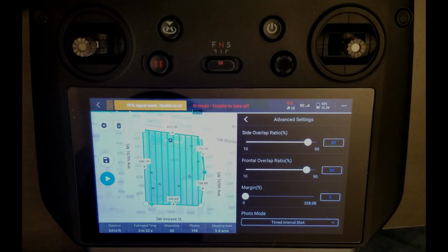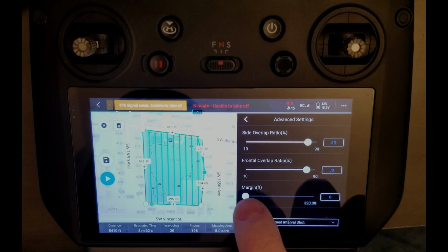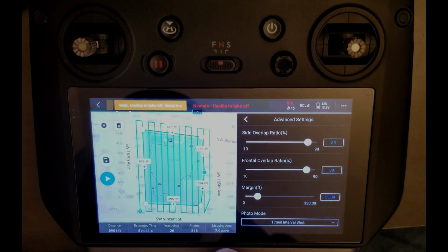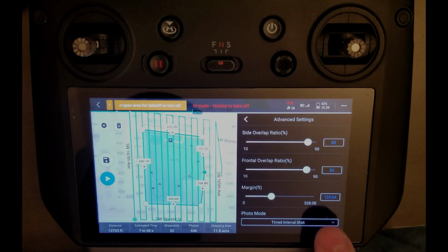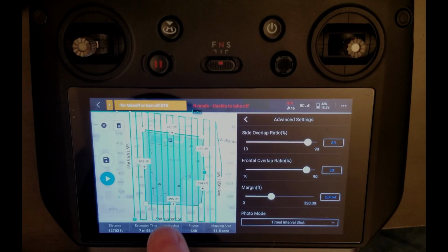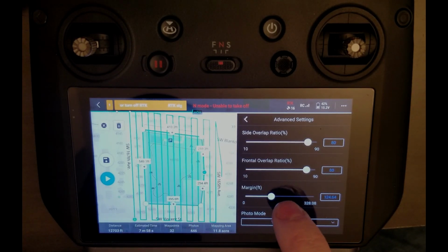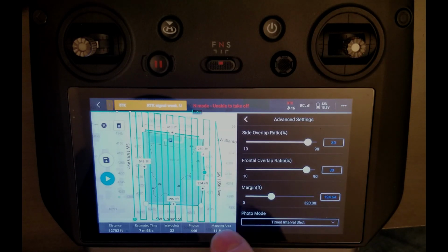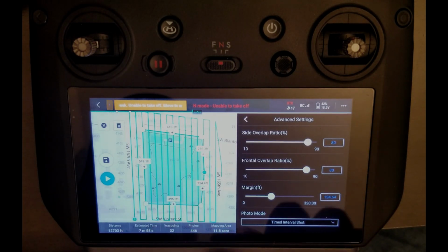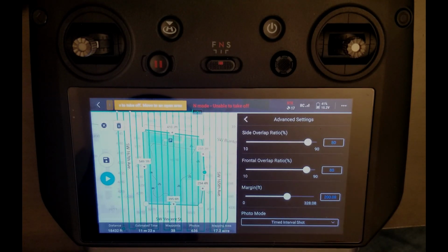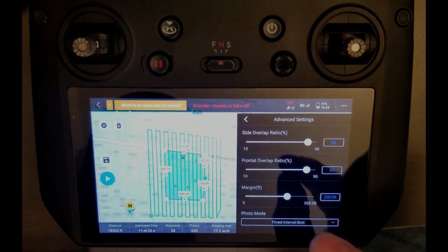With a slider bar or picking, I can now determine a distance beyond my project to add additional flight lines. As you see within this one, 124 feet beyond our project, I've now got additional flight lines. This creates an imaginary box 124 feet outside my project site and adds additional flights.